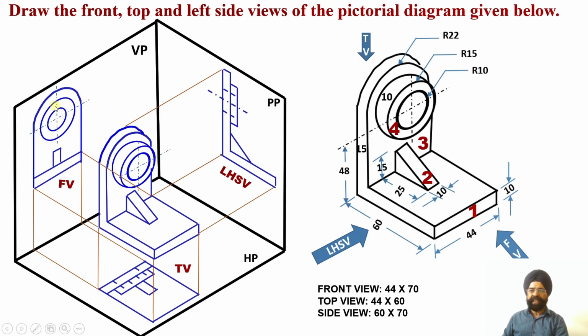Then you have the third surface over here, which is this one, the flatter surface. I told you it is beyond the circular portion, that is, on the outer periphery. So you can see it is this surface over there, and it excludes this web, and it excludes this projected circular web over here. So this surface number 3 is this surface. Since this surface happens to be parallel to the vertical plane, on the vertical plane I have been able to obtain the true shape of this surface.